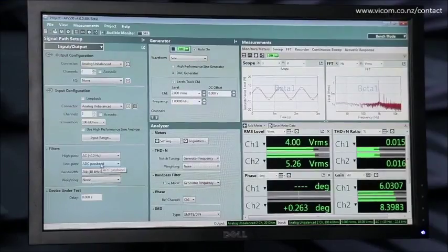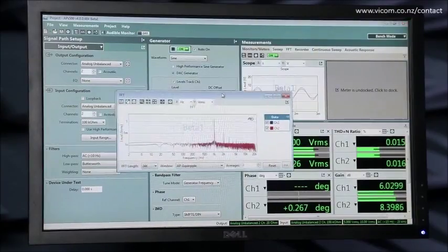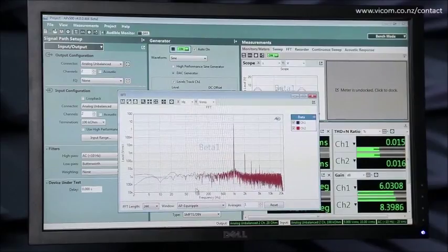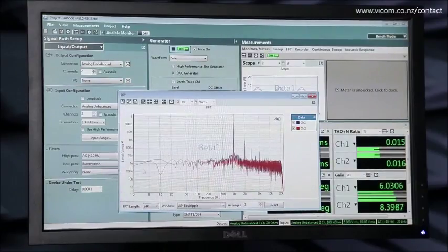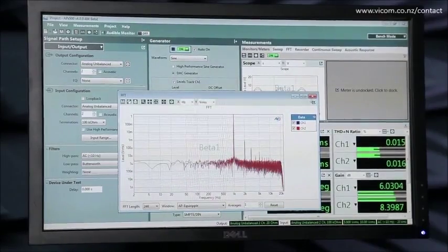So over here we have a low pass control, and there's some choices, including custom choices, where you say, well, I would like a Butterworth filter and I want it at 20 kilohertz. So you can just type in that corner frequency, and now the system has been set up with a Butterworth. And let me show you that in the frequency domain. I can show you that by making this thing a bit bigger here, and you can see, oh look, there's a corner. You can see the signal rolling off there at 20 kilohertz.